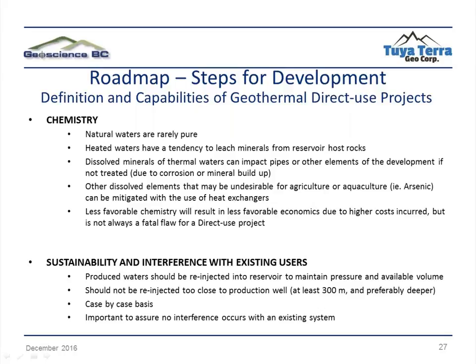We need to maintain the pressure so that we can continue to produce fluid, but we can't have it too close so that we're cooling the system that we're already trying to tap, but we need to have it close enough that it's giving pressure support. So these are part of the engineering considerations that go into a development project.